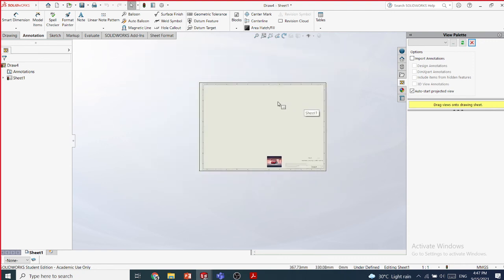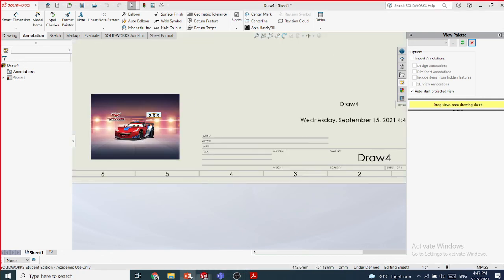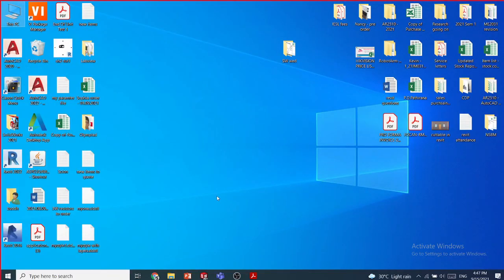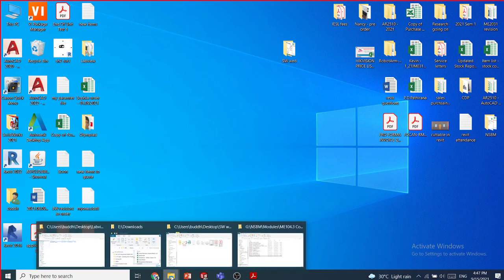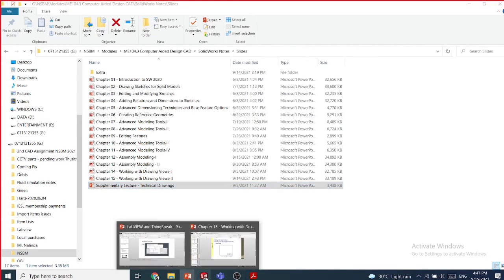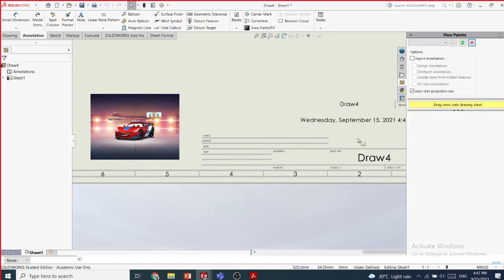So we need to know modeling, we need to know assembly, and we need to produce a good drawing. So remember to give the drawing projections. Okay, whether you are using third angle or first angle, we talked about first angle or third angle projections, those things can be given at a side of the drawing. Put this part somewhere. That symbol, drawing symbol, projection type. Okay, let's give it somewhere here and type your name, the drawing name,